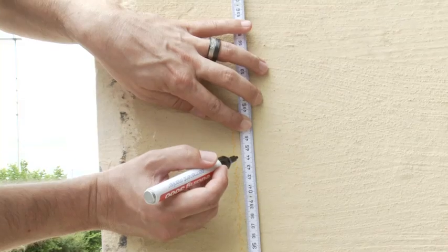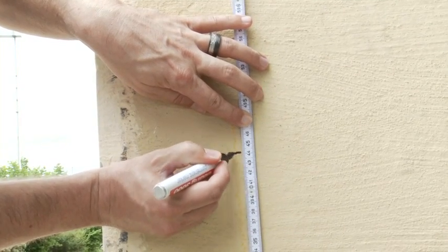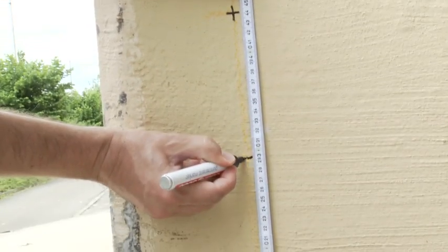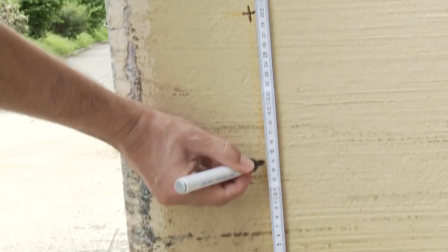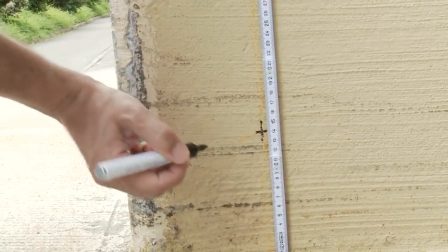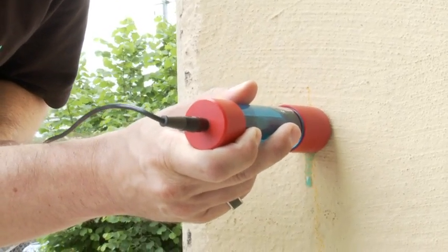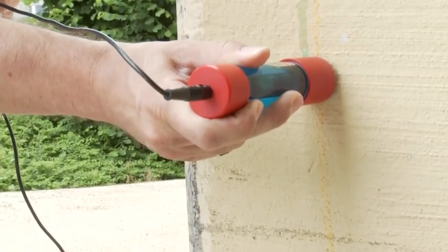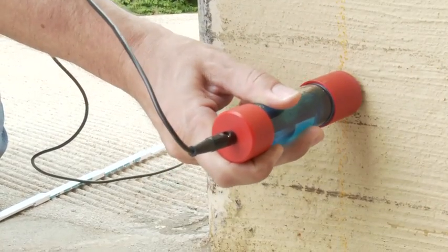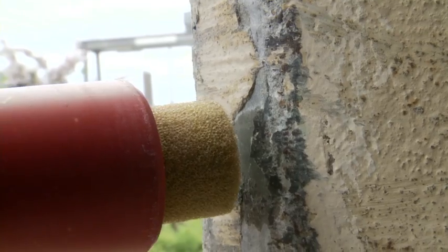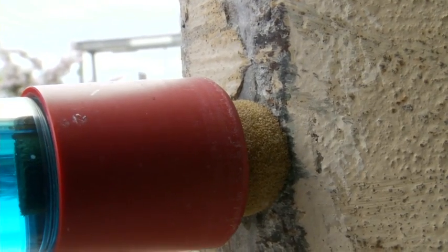When preparing the test surface, it is recommended to mark out a grid on the surface corresponding to the grid you wish to use. It is always necessary to check whether or not a measurement can be made through a coating. To do this, potential should be measured at a few locations, in the first place through the coating and then with the coating removed.